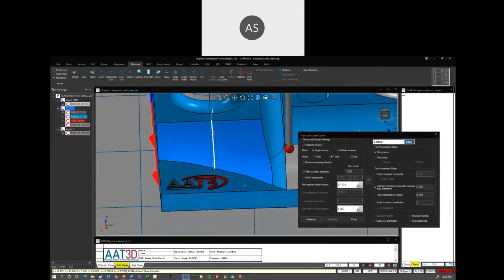I want multiple sections. So choose the multiple sections option, define my first boundary, define my last boundary. Okay, now I've got, you can see here, I've got 4 cross sections. So the cross sections are either based off of the increment number set here. So these are approximately 10 millimeters apart. I prefer to use the number of sections option, which says, you know what, just give me 3.